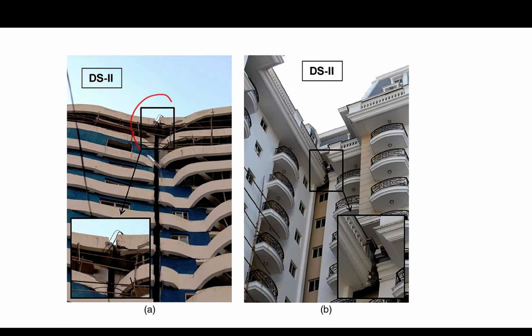As you can see here, for example, this is two buildings and the separation was not enough, so we found that there was a seismic pounding at the roof, and you can find the amount of damage here. Also, it happened here. If we magnify it, you can find that there is a seismic pounding. So it happens in whatever earthquake, as long as there are structures that do not have sufficient separation between them.